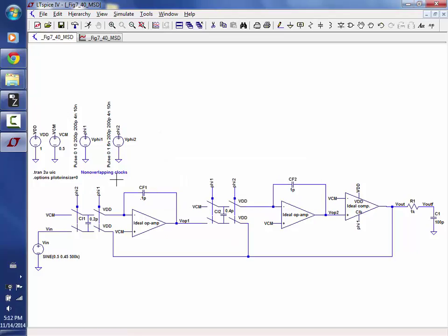I'm missing the point. What are we trying to do here with the outputs of the integrator and all this stuff with all the equations? What's the whole point? Yeah, we want to get as big a swing out as possible without saturating. We want those signals to swing big because then we have more forward gain and it's easier for us to control things. We could just design this so we get little teeny tiny signals here, never have to worry about the integrator saturating, but that's not what we want because then the comparator has to be ideal or has to work better. We don't want that.